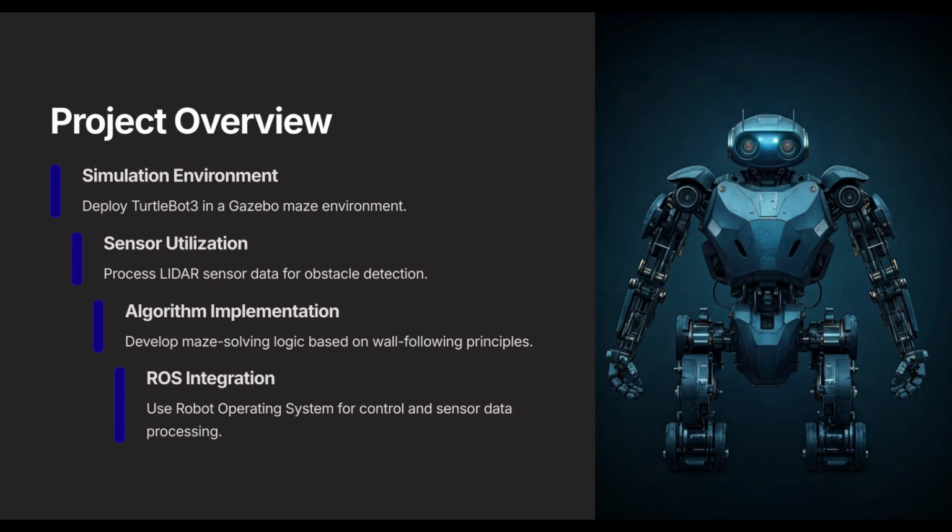This project was broken down into several components. First, we deployed a TurtleBot3 robot into a custom maze environment inside Gazebo. Then, we processed real-time LiDAR sensor data to detect walls and obstacles. We implemented a wall-following maze-solving algorithm based on reactive controls instead of using a global path planning algorithm such as A*. Finally, we used the Robot Operating System, or ROS, for managing sensor data, movement control, and communication between nodes.